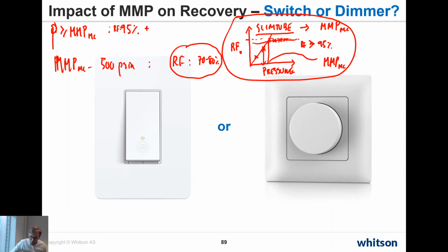And also the other thing to mention is that this recovery efficiency or recovery factor number is just one of 3 things that contribute to enhanced oil recovery, call it efficiency, because you need to have also the volumetric sweep efficiency. So if you can't get the gas to obviously contact the oil and sweep through the media, it doesn't matter how large this recovery factor is.